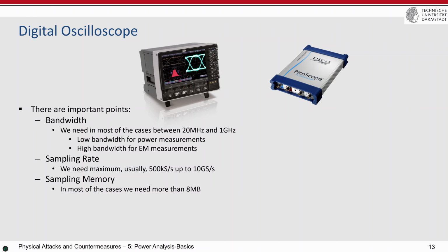Yeah, and if you go for 10 gigasample per second, the oscilloscope that you buy with that price, 50,000, the memory is, at the moment, when you look at the market, an oscilloscope with 10 gigasample per second usually has 256 megabytes of memory. Just 256 mega, not giga, mega. And if you want to upgrade it to something with, let's say, double or 1 gigabyte, then you have to pay around 20,000 euros just for the memory.